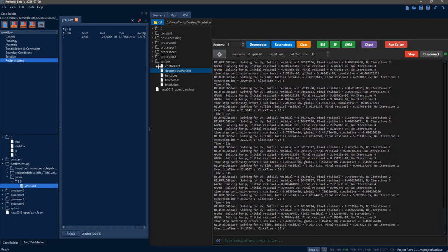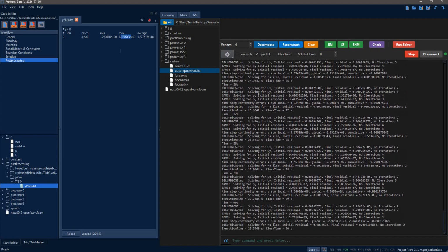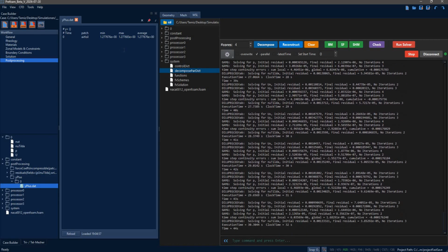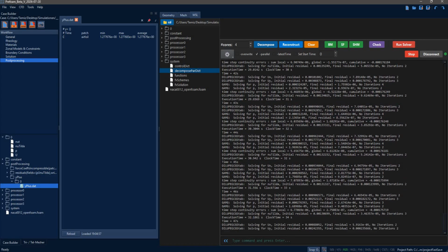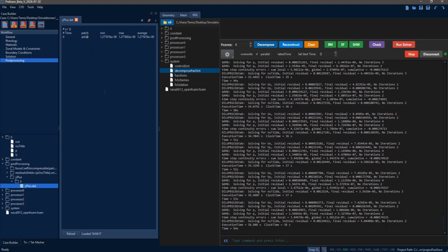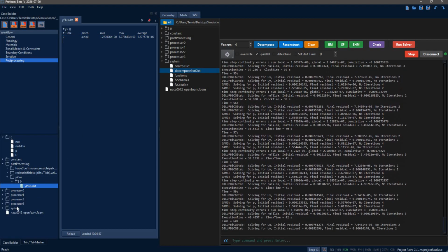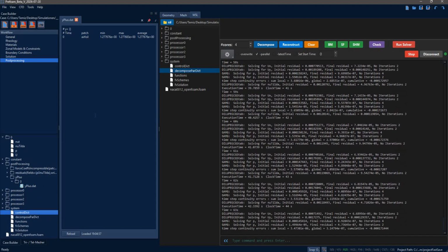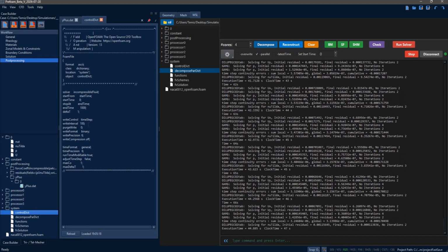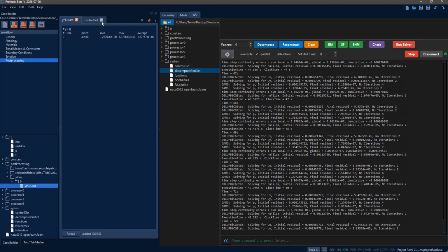Now y plus will create this entry. We are aiming for y plus under 1 for this case, and I ignore the 0 entry over here. Yeah, we write every 100 iterations, so I need to wait for 100 iterations.